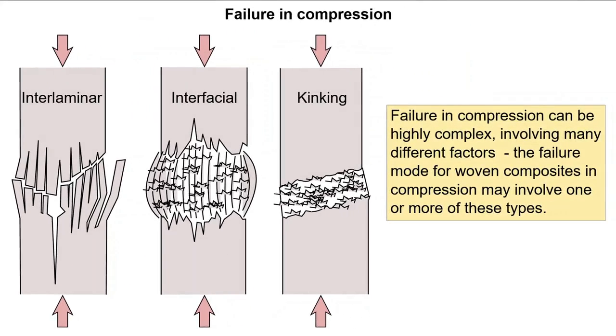Interlaminar failure, whereby layers of composite sheets buckle and fail between each layer, as this is where the matrix fails first. If interlaminar failure is avoided, then the next mode will be the failure of the interface between the matrix and reinforcement on a local or global basis. Finally, if the matrix also fails globally, then the fibers can kink while at the interface in some regions along their length stays intact. It is likely all three of these modes took place during the crash testing depicted earlier.